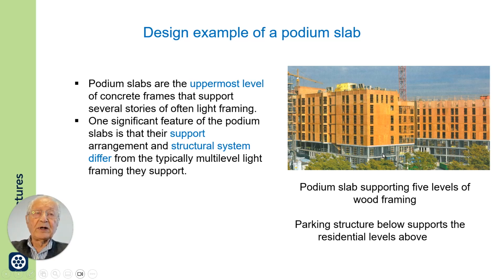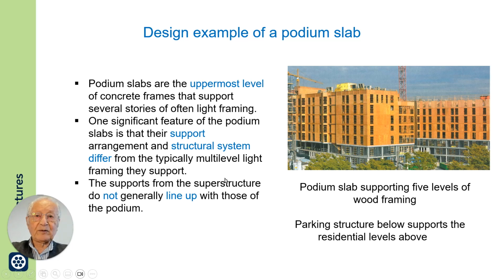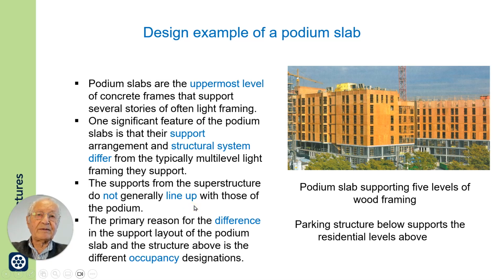So you end up with a lot of concentrated loads resting not necessarily on supports of the podium, but somewhere in the span. The supports from the superstructure do not generally line up with those of the podium.